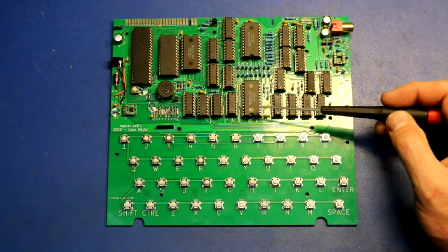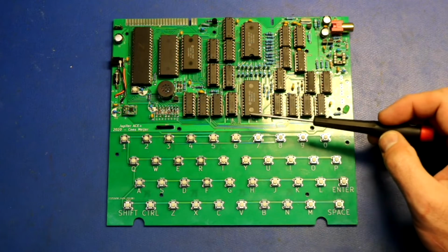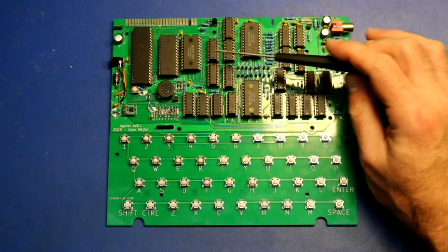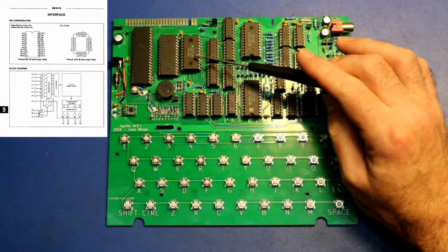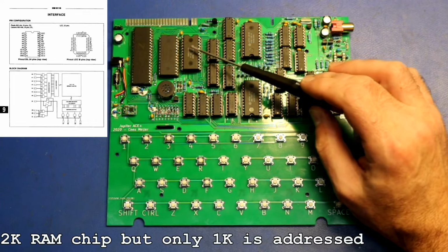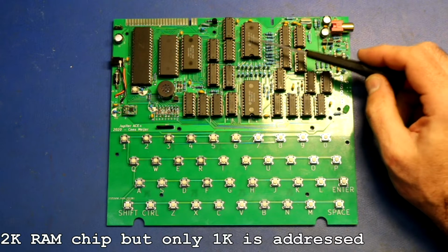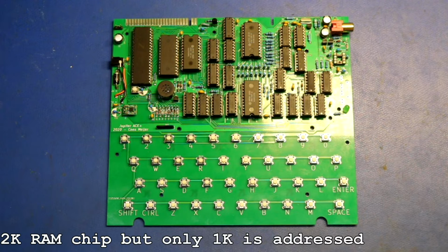Now the original Jupiter Ace design used 2114 RAM chips, which are 4-bit chips. And the author of this project changed that to use these 6116s, which are a little bit more readily available, and they are 8-bit RAM chips. So you've got 1K here, 768 of that is your program RAM, then you've got 1K here for the video and the pad, and then another 1K down here for the character generator RAM.